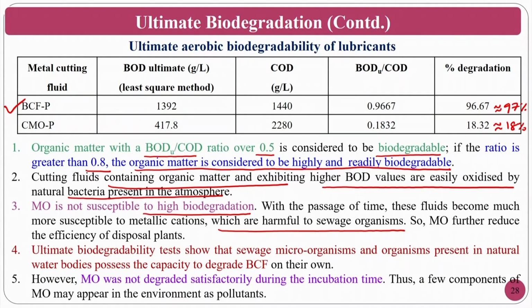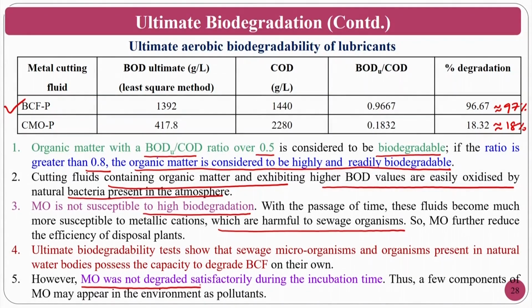That means that the microorganisms that are there in the sewage or in the pure water bodies, or the river bodies or the lake bodies, are capable enough to degrade the biocutting fluid, but not the mineral oil. However, mineral oil is not degradable satisfactorily during the incubation time. This is what that means.